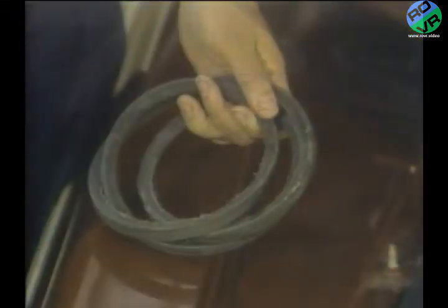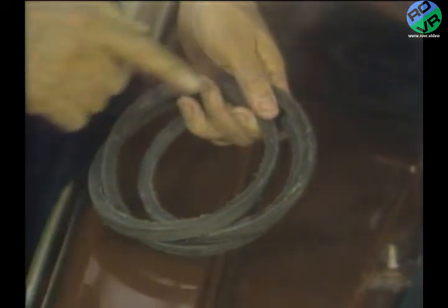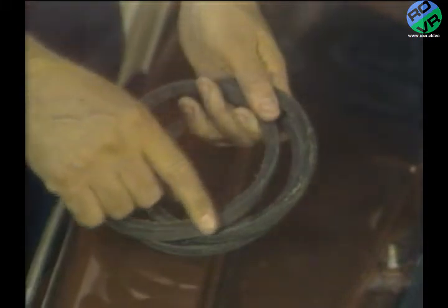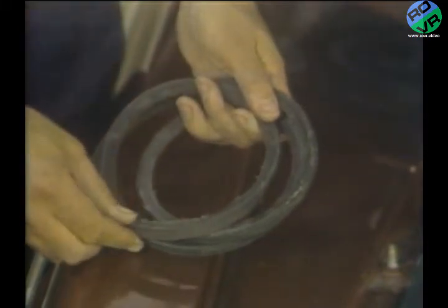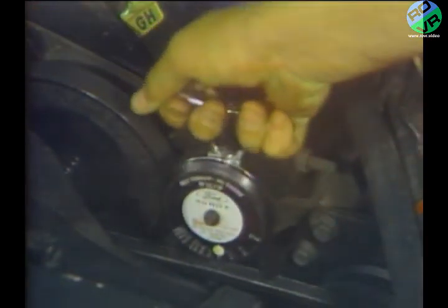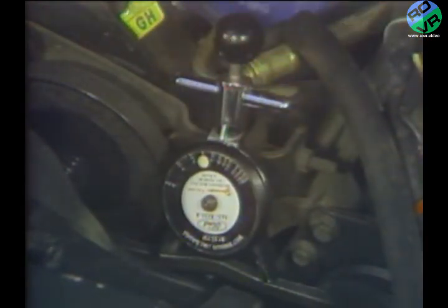Common engine and accessory NVH problems can include vibrations in the accessory driveline system. When this occurs, inspect for broken or frayed belts. Checking accessory belts for the proper tension can also uncover and eliminate engine area noise and vibration symptoms.